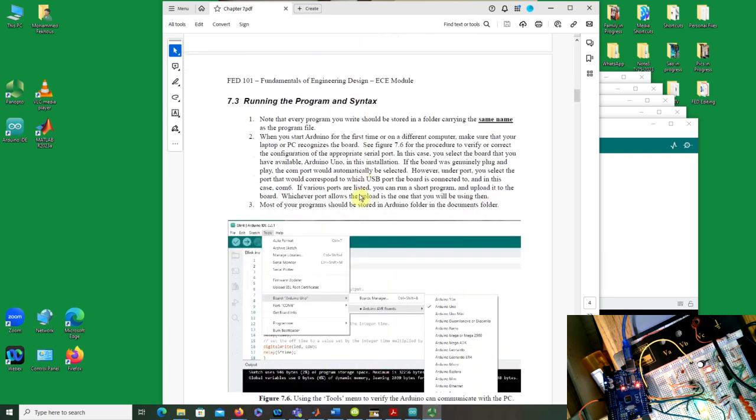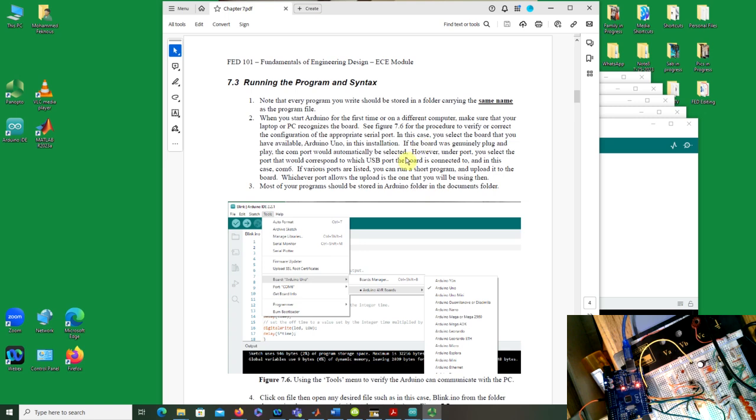So, to be able to run the programs associated with Arduino, first you have to go to Tools and choose the board. It depends on the computers and on the boards themselves. Sometimes there's the original Arduino, or compatibles. In some cases, the software will be kind of plug and play, meaning it will recognize the board and automatically tell you that the board has been recognized. Whereas in this case, I had to go to this choice here and select Arduino Uno.